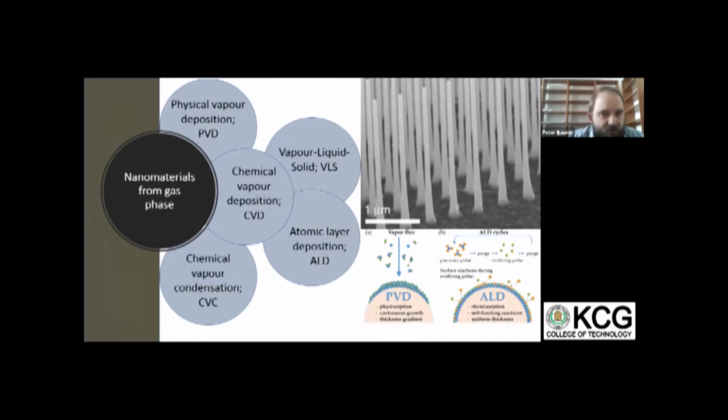And a very interesting technique for me is ALD, atomic layer deposition, when we are able to prepare a coating with atomic thick or molecular thick thickness. So we can build up the coating in this way. We say that we would like to prepare a one atomic layer thick coating, and we are able to prepare it using ALD.